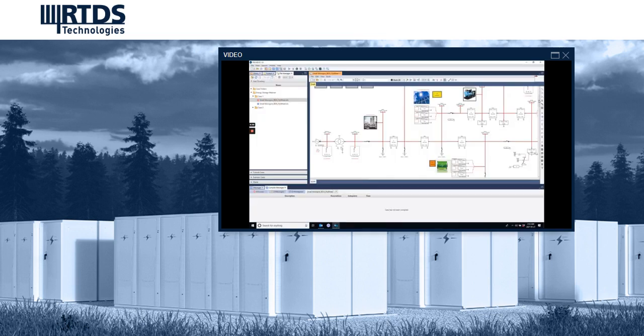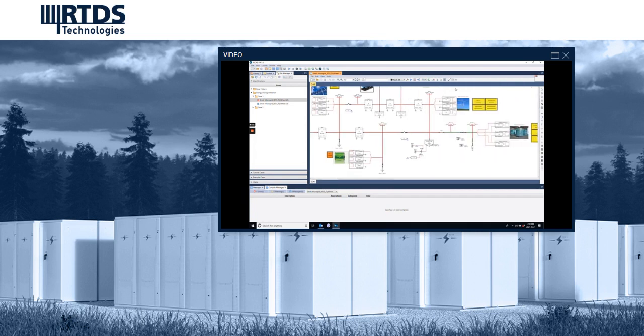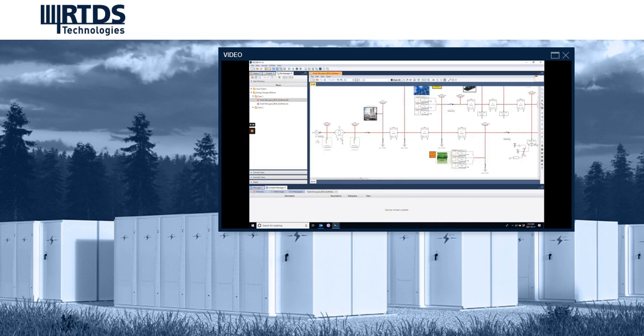In this section, a real-time demonstration of a microgrid with a battery, a PV, a diesel, a wind, and flywheel renewable and distributed energy resource will be discussed. The microgrid has very short transmission lines, less than 5 kilometers, so a pi section model is used to represent the transmission lines in the microgrid. The sequence data for the transmission line can be entered in the parameter tab of the pi section model.